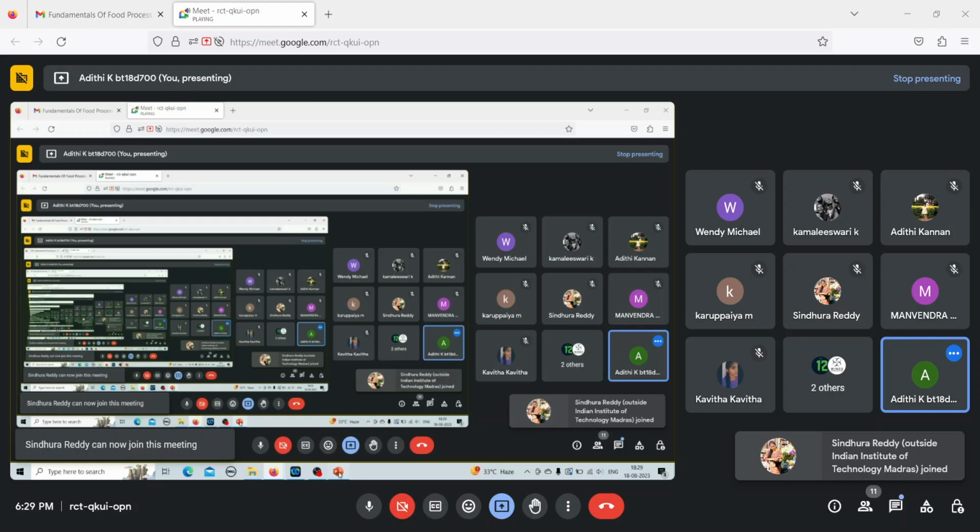So if I am substituting the values, Q is 51.6 kilojoules divided by the overall heat transfer coefficient, which is given as 1756 watt per meter square degree Celsius, into delta T, which is Ts, that is the temperature of steam, minus T1, which is the temperature of the evaporator. So 375 minus 323, which will give me an area of 0.57 meter square. Is this part clear, how to calculate the area?